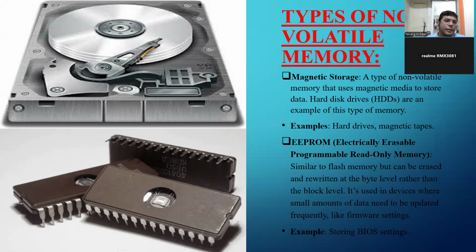EEPROM, electrically erasable programmable read-only memory. It is similar to flash memory, but it can be erased and rewritten at the byte level rather than the block level. Generally, flash memory works at the block level, but in EEPROM, erasing and rewriting is done at the byte level. It's used in devices where a small amount of data needs to be updated frequently, like firmware systems, for example BIOS settings.